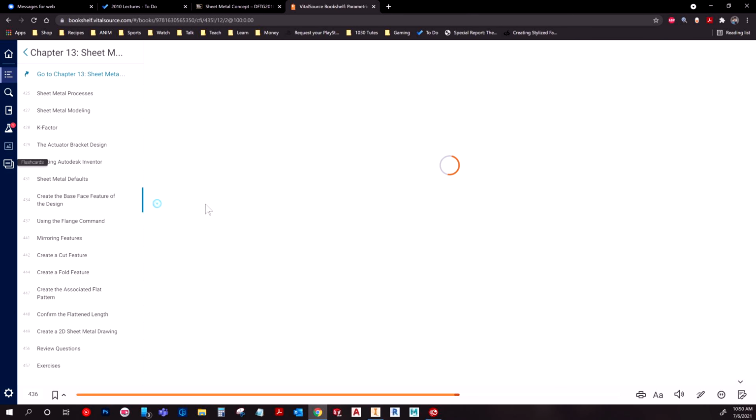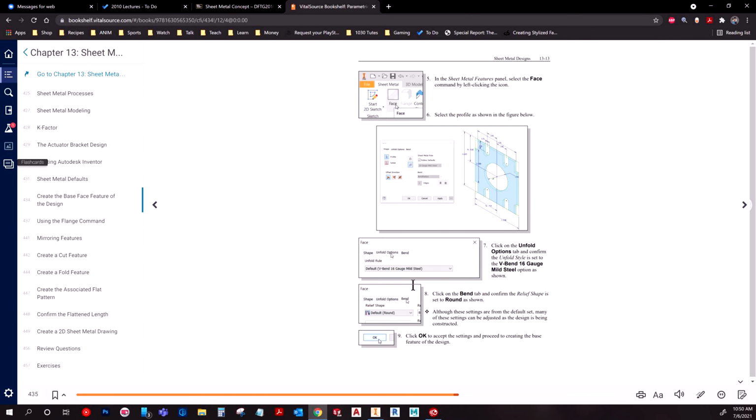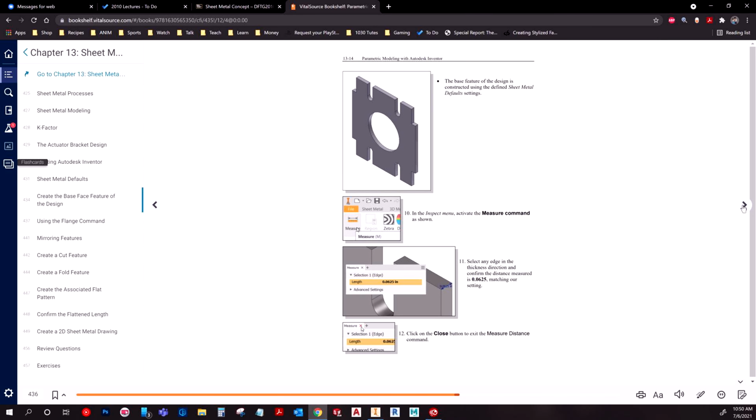Now this is an interesting part too. When you work with a regular part, usually you extrude it however thick you want, and that's that. But with sheet metal, you use the face command instead, so there's no need for that. It pulls the default, so you're just clicking a profile and it makes a shape. So sheet metal works almost completely different, and it's a whole discipline in itself. But you're going to have to get familiar with those tools, and I'll try to demonstrate all those.